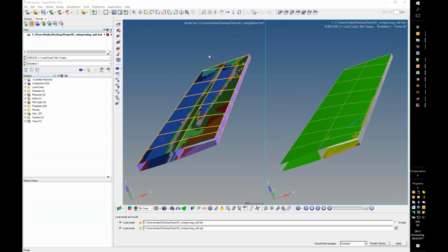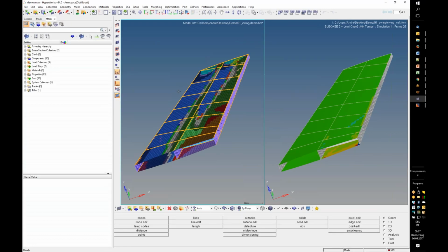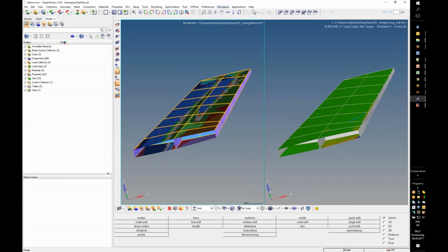So when you're using HyperWorks 14 and the latest patch 130, you will find the possibility to go in the preferences to user profiles, engineering solutions, and there's aerospace as well. When you work in this profile, you'll see the aerospace toolbar up here. The ESAComp related features are hidden in the certification menu. There you'll find the ESAComp export and ESAComp import.